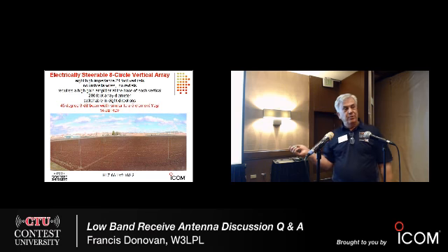Definitely when you are trying to get very high performance receiving antennas, you don't want to put this antenna near towers. You don't want to put it near power lines because you're going to lose some of that RDF, and it's hardly worth the time and trouble to put up an antenna that has 3 or 4 dB of an advantage and then lose it because of a nearby tower or a nearby power line.